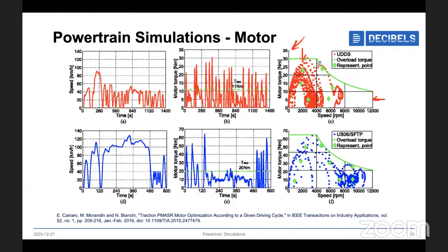Your efficiency maps will be something like this. Sorry, both are red in color. Let's say this is 90 percent, 85 percent, 80 percent, 75 percent, like this. So you'll get to know, okay, I'm operating most of the points in the 75% region. So how can I move these operating points to the 90% region? It can be either by varying the voltage and currents, or by varying the gear ratios. You can do all those analyses using this particular simulation part.